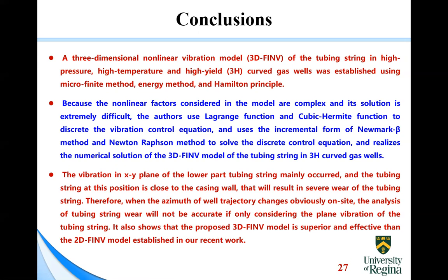So we use the Lagrange functions and cubic Hamilton functions to discretize the vibration equation, and use the incremental forms of the Newmark beta method and the Newton-Raphson method to solve the discrete control equation and realize the numerical solution of the three-dimensional nonlinear model of the tube string in high pressure, high temperature gas wells.